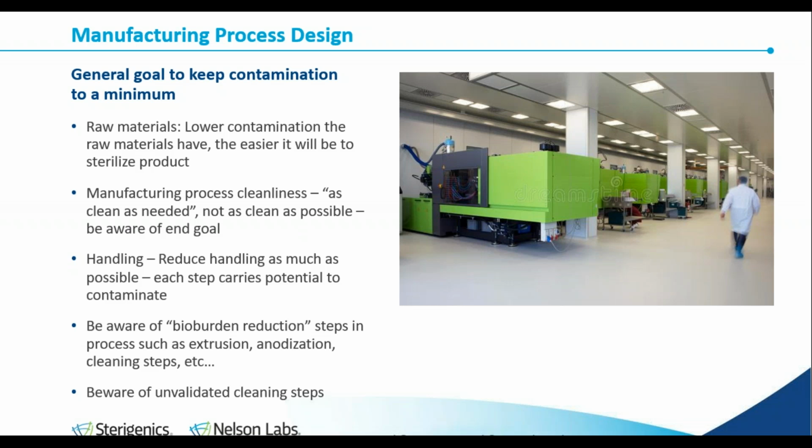While that might be needed, or as close as we can get to it, for an aseptic fill, alternatively, if you're using a terminal sterilization method, there may be some latitude, depending on the product functionality when exposed to that method, to allow for some microorganisms to be present. And we have to be aware of what our sterilization method can actually handle to determine how robust we need the manufacturing process to be from a microbial elimination standpoint.